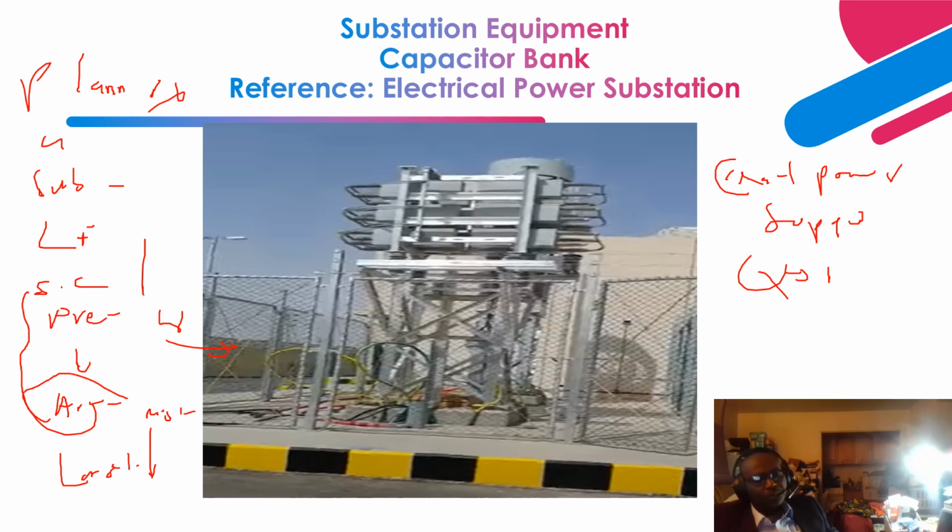Then they do insulation coordination studies, and that itself ties into the selection of surge arresters and also the location of lightning arresters on the towers to protect the substation.